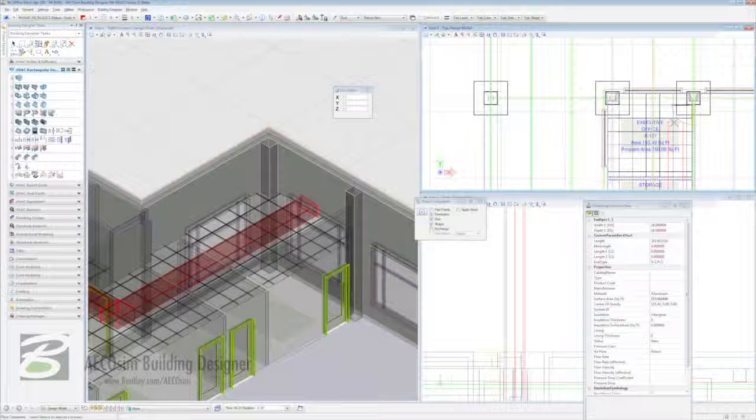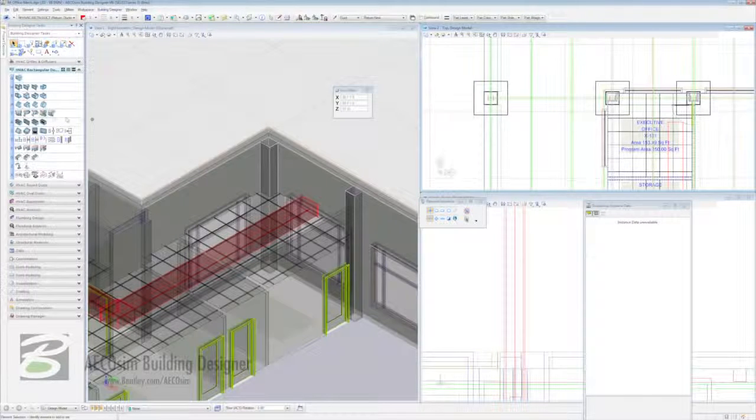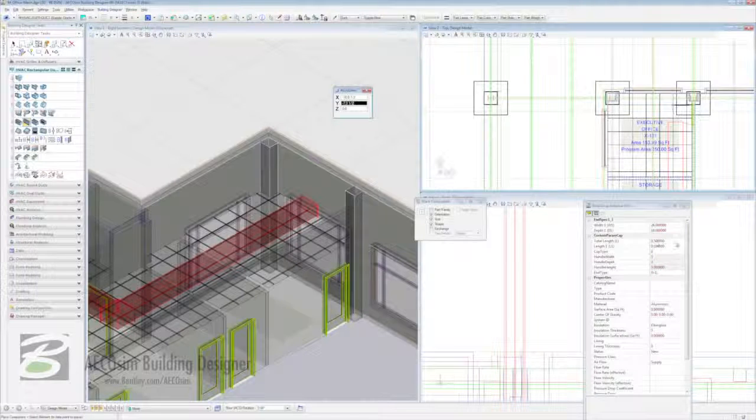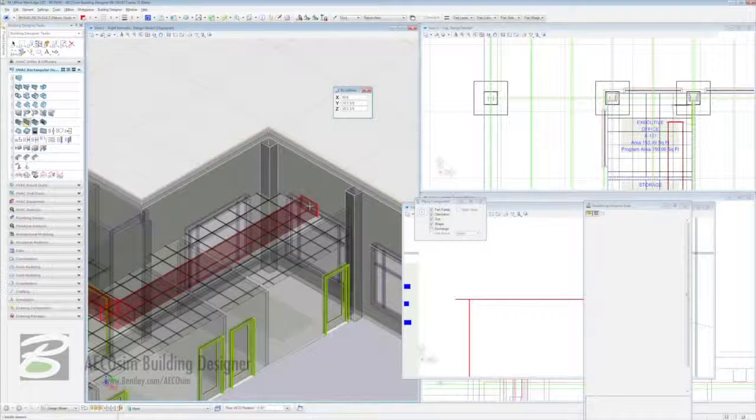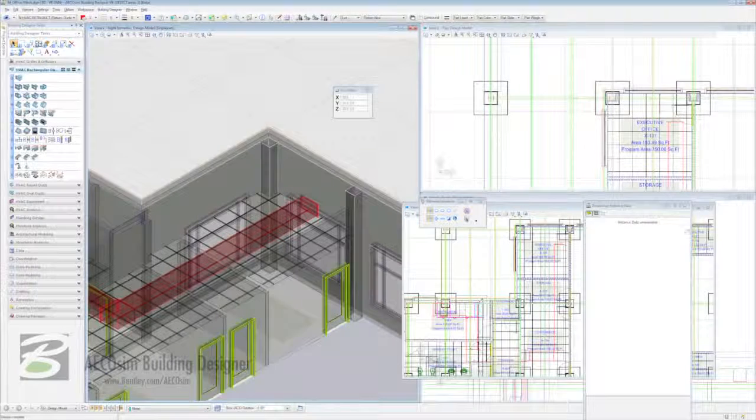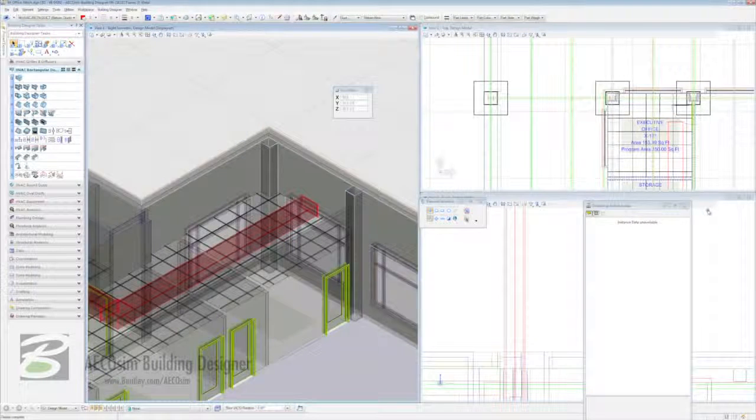Now we can right click to reset, and we can come across to our task-based interface to place a rectangular cap, and our total length must be 0.5 and our length is 0.1. With that we can come into our place component, check part and family, and then we just move in here to the yellow cross and click once more to place. And now we've placed our end cap on our return.